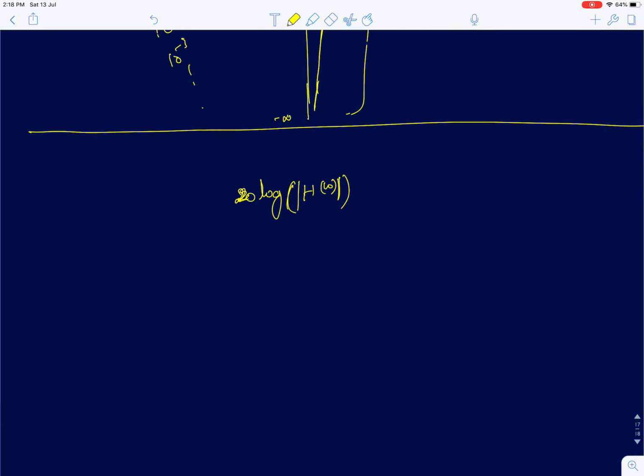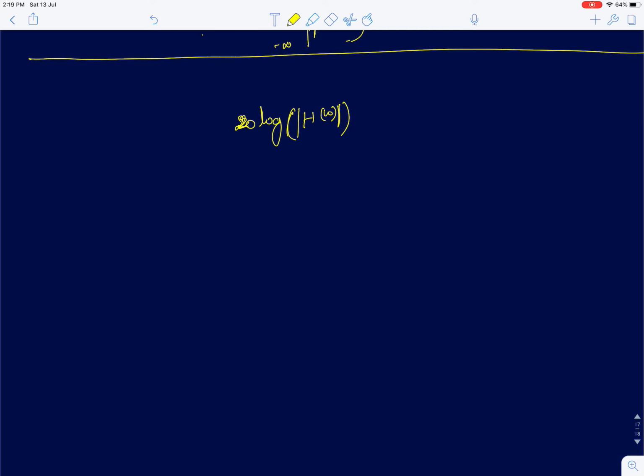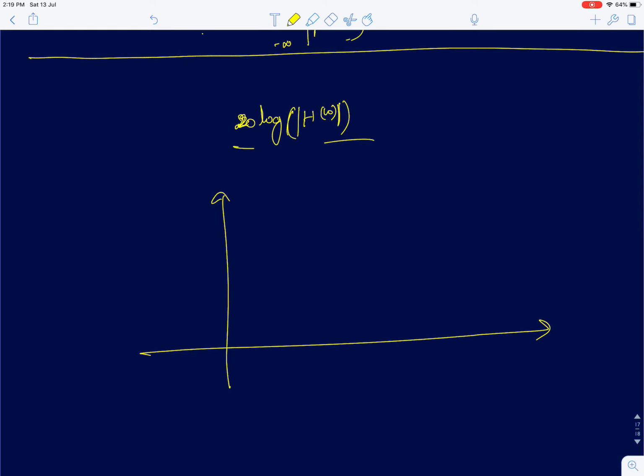Frequency already varies from 0 to infinity, there is no doubt. But the amplitude has a small variation, 1 to 0. As I told you, as far as amplifiers are concerned, a variation from 0.1 to 0.01 is just as significant as 1 to 0.1. Which is why we apply logarithms for the amplitude. So now we plot both frequency and amplitude on a log scale. Such a plot is called a Bode plot.